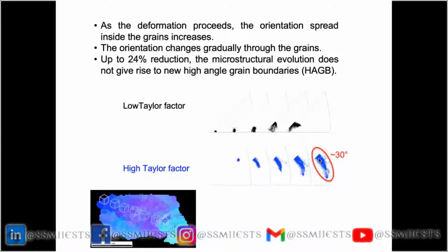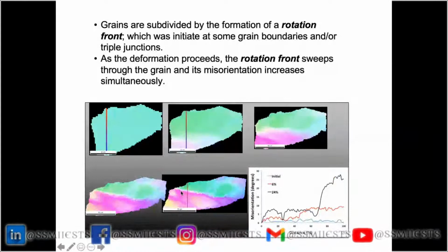You also have, sometimes, these high angle grain boundaries appearing. And this is really the process of plastic deformation generating high angle grain boundaries. So you have grain refinement. This has given rise to the process, probably some of you have heard already about it, severe plastic deformation.